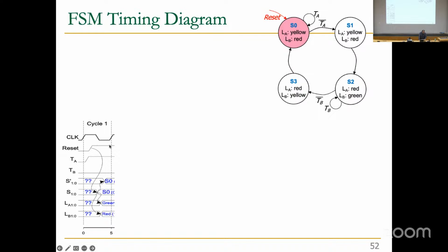The reset signal that we are considering here is actually asynchronous. We discussed synchronous and asynchronous circuits yesterday. This FSM is mostly synchronous because it works with clock, but the reset signal is asynchronous, meaning that whenever you trigger reset, you reset the whole system. For reset, you don't wait for a clock cycle.